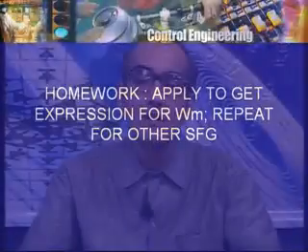And then you can repeat this with the other signal flow graph that we drew for the same system, choosing a somewhat different arrangement, but both omega m and Ia as the output nodes. Apply it to that signal flow graph and check that you will get the same expression. So whichever way you draw the signal flow graph, the final answer will be the same, and that's the way it should be, because we don't expect that we will get 2 or more differing answers.